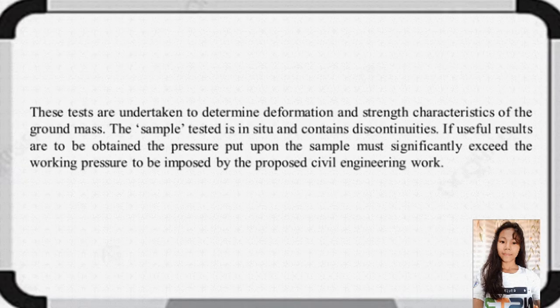These tests are undertaken to determine the deformation and strength characteristics of the ground mass. The sample, tested in situ, contains discontinuities. If useful results are to be obtained, the pressure put upon the sample must significantly exceed the working pressure to be imposed by the proposed civil engineering work.